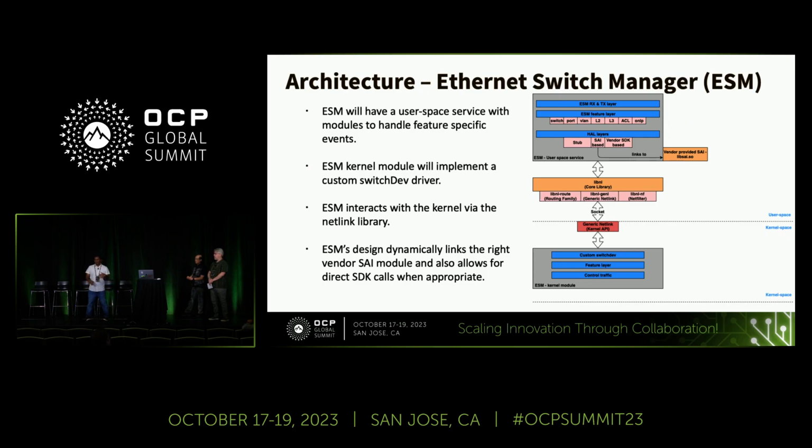The user space agent will have the ability to do TX/RX with the kernel, like I mentioned. It will also have per-feature modules to handle events that are happening in the kernel, eventually translate them into a language that the ASIC understands and program the register set as required.